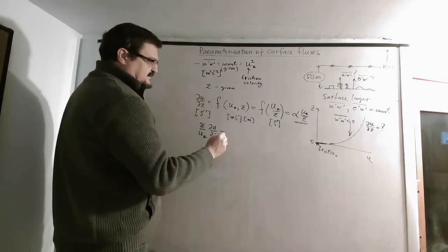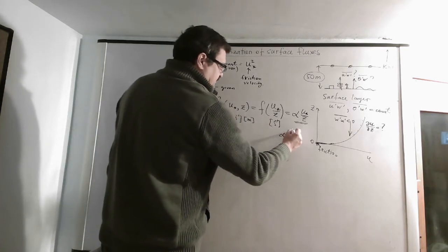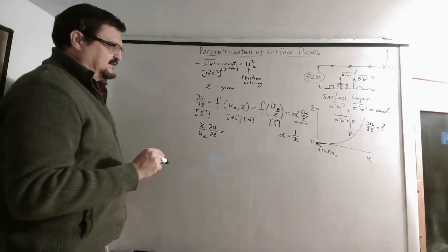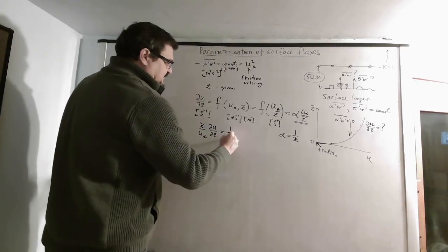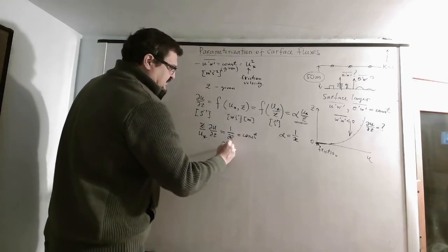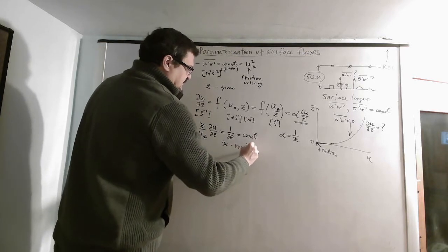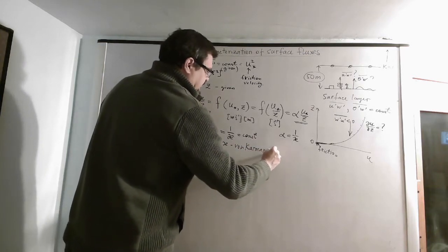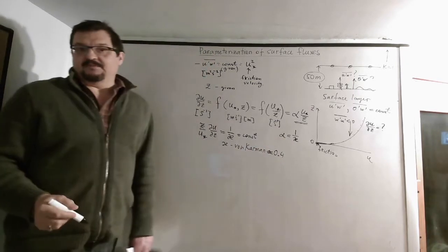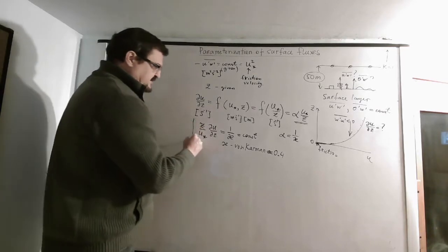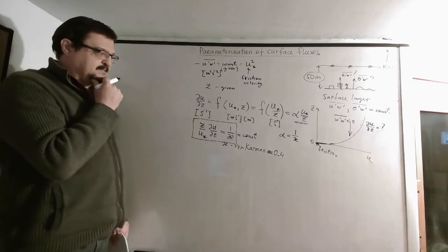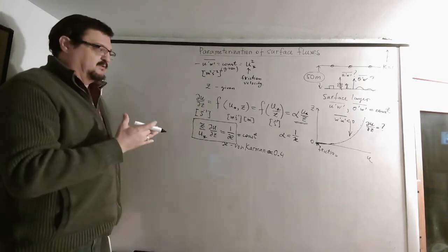And this constant alpha, which I noted here, for some reasons that are going to be known later, equals some constant 1 over kappa. It is a constant, and this kappa is called the von Karman constant, and it's approximately 0.4. And you find the 0.4 from experiment, because this law of nature does not change on a specific case that you're looking at.